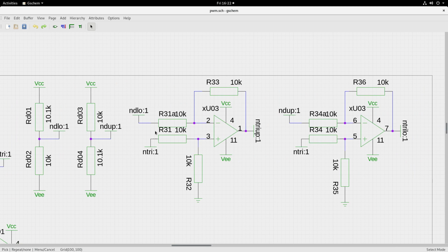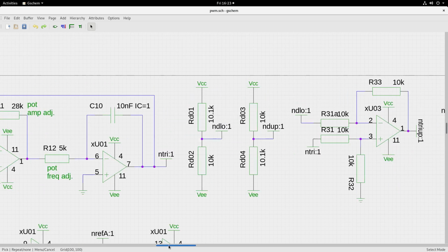And then use the other one to subtract through a diff amp stage. I get the triangle lower. So this will be VC plus and this will be VC minus, carrier plus and carrier minus. Now use these two upper and lower carriers to obtain the PWM with dead band or the dead time.